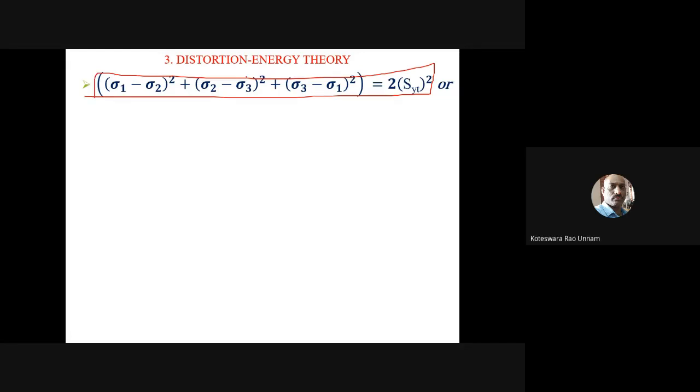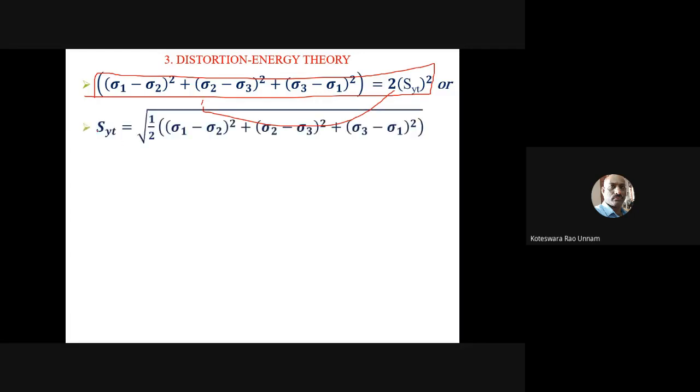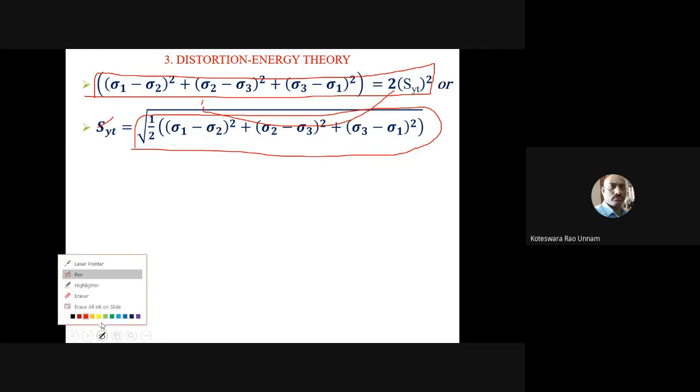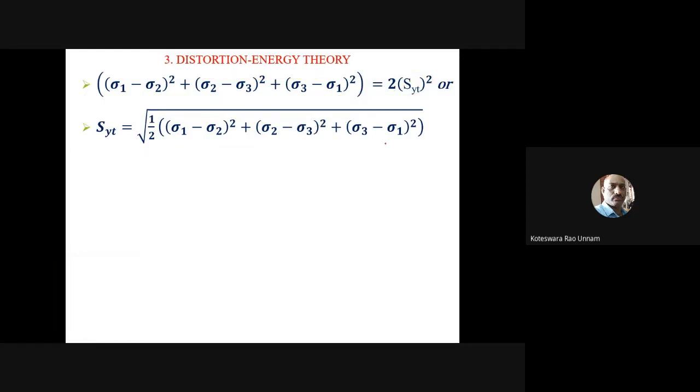So for triaxial state of stress, I can further simplify this. I'll bring this 2 to this side and write in terms of SYT. If I simplify this one further, this is going to be the failure equation, or design equation I can say, for distortion strain energy in case of triaxial loading.